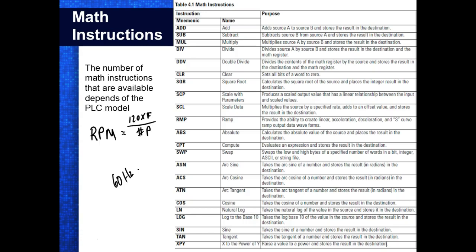Now, 3,600. So that's the fastest we can run, and that's if it's 2 poles. This is a 4-pole motor right there. We use half this, so that'd be 1,800. But if you look at the nameplate, I think it says 1,725. So your rotor can never run at the same speed because we have to have a difference in speed between the two. Like I said, they call it slip.